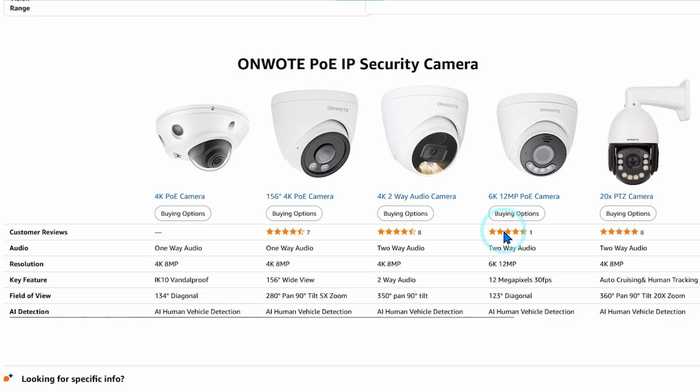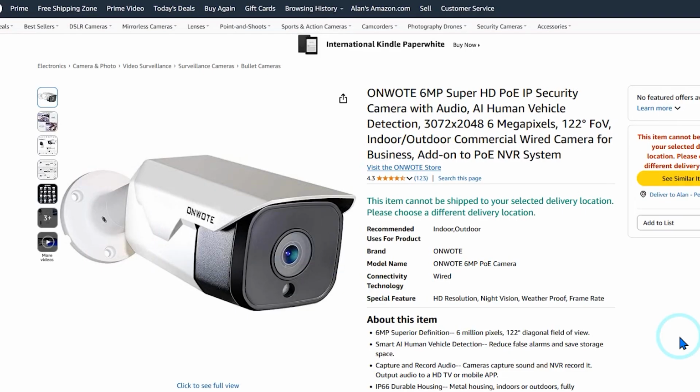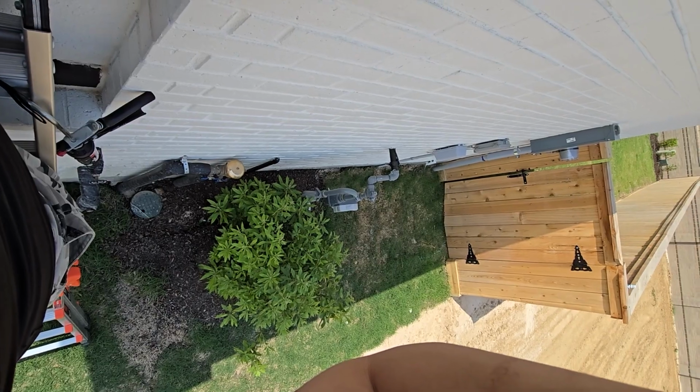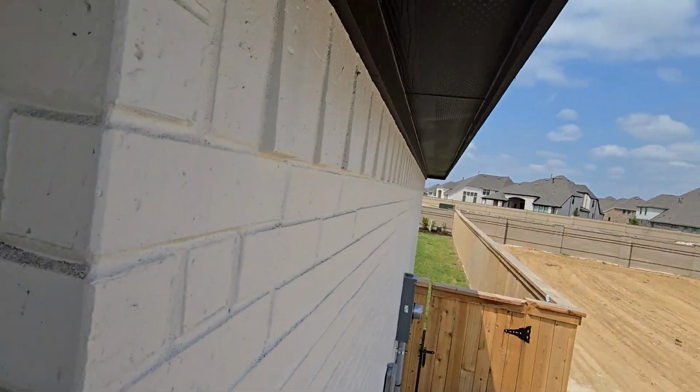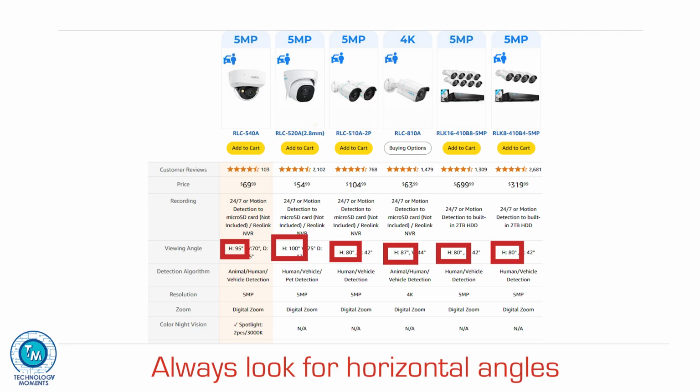These type of cameras are widely available and we can even interchange them with other brands or models, exactly as we ended up doing with our system, depending on the viewing angle and the resolution we want in a given location. The viewing angles are generally exaggerated by the manufacturers, who consider the angle to be the angle that gives us diagonally. You can estimate about 20 degrees less than what manufacturers claim.